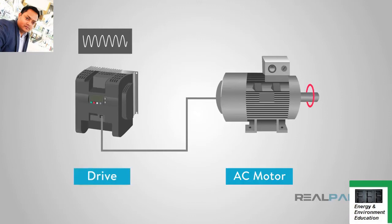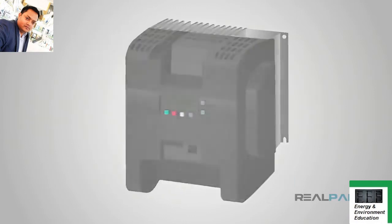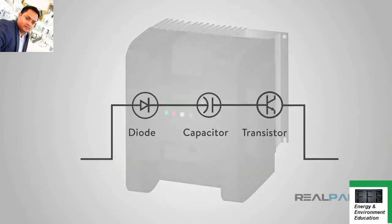They work by adjusting the frequency of the motor to adjust the RPMs. To do this, a VFD will actually convert the voltage twice. First, it converts our three-phase AC to DC. This is accomplished with diodes. Then it cleans the DC with a capacitor. Next, it will convert the DC to AC. This is accomplished with transistors acting as switches.